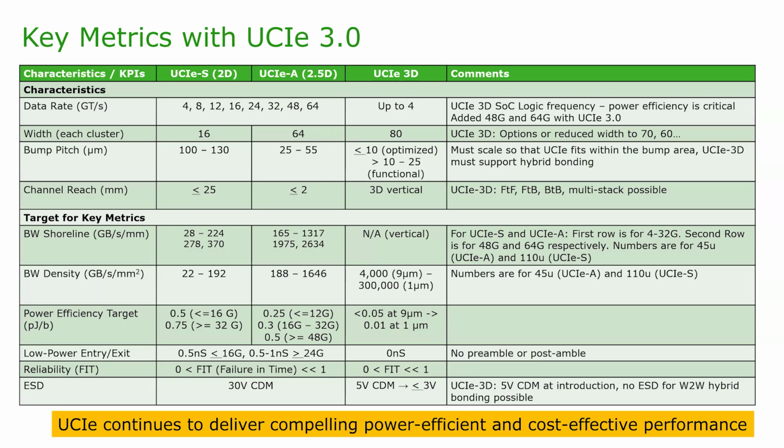Now, what this results in is linear power consumption with bandwidth usage. In other words, if I need 10% bandwidth of the peak bandwidth, I should ideally consume 10% of the max power, right? And this gets you closer to that. Now contrast that to external interconnects, where exit from this low power state takes several microseconds because the circuits are so complex.